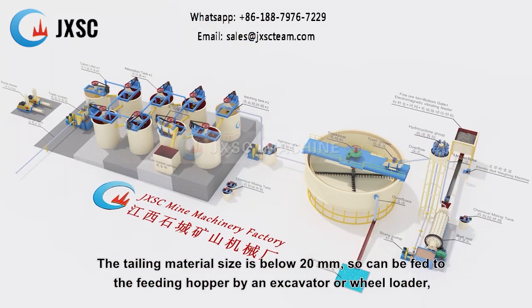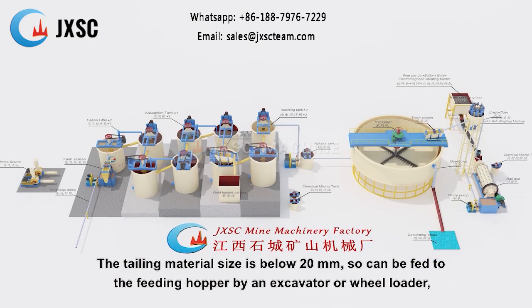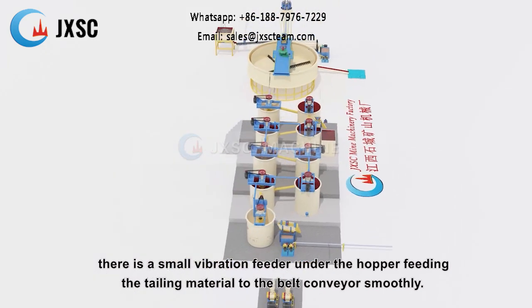1. Feeding system. The tailing material size is below 20 millimeters, so it can be fed to the feeding hopper by an excavator or wheel loader. There is a small vibration feeder under the hopper feeding the tailing material to the belt conveyor smoothly.